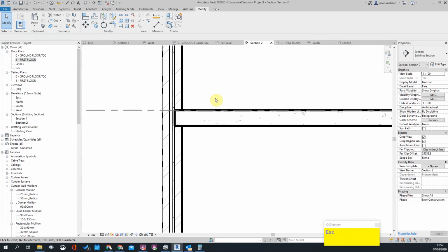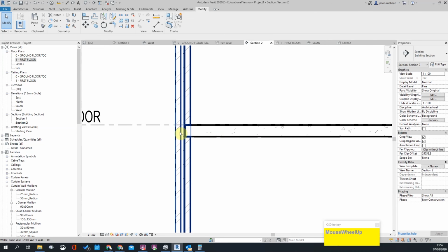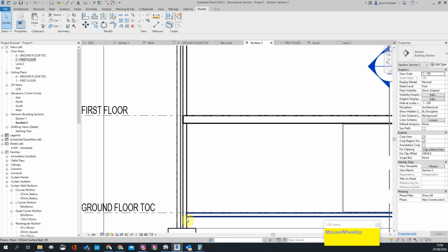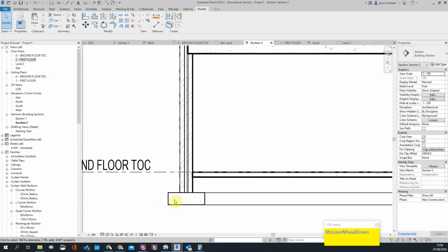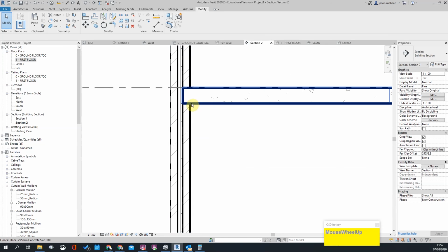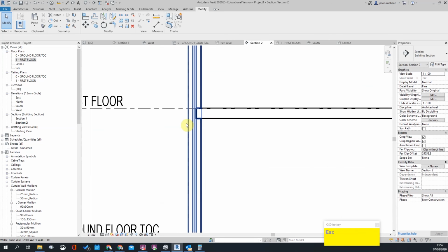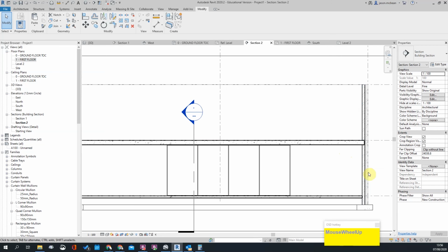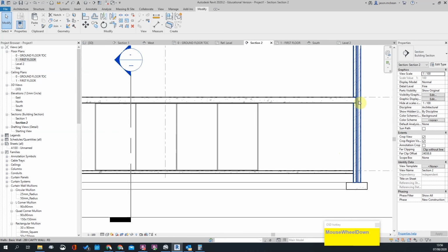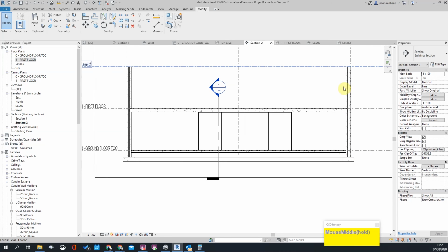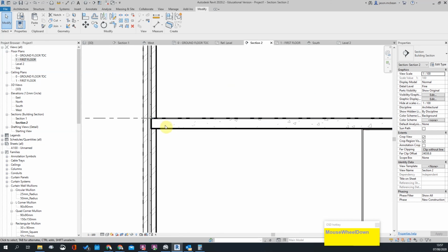Join that with that. So here's your concrete. You might find there's a column that goes in here. So this concrete will go past. So these skins get built up to there. It's different with your surface bed. Your surface bed doesn't go into the wall itself because these come off your foundations. But these, and then they put a steel hanger in here to carry the external skin. Maybe because this external skin can't go too high. So there needs to be some way to secure each level's external face brick, for example. Okay, there's different ways to do it. All right, so that's that in a nutshell.